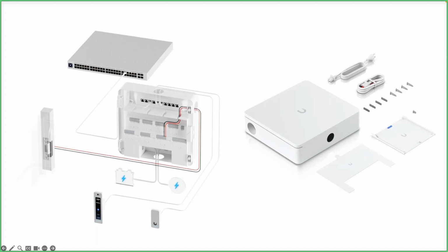And because it's just using PoE, we don't need to have a battery on at the actual hub itself. The limitation here is obviously still 100 meters in terms of Ethernet connectivity and your PoE range there. The dry contacts could potentially go a little bit further depending on how you're setting this up, but this is primarily the way to power it up.